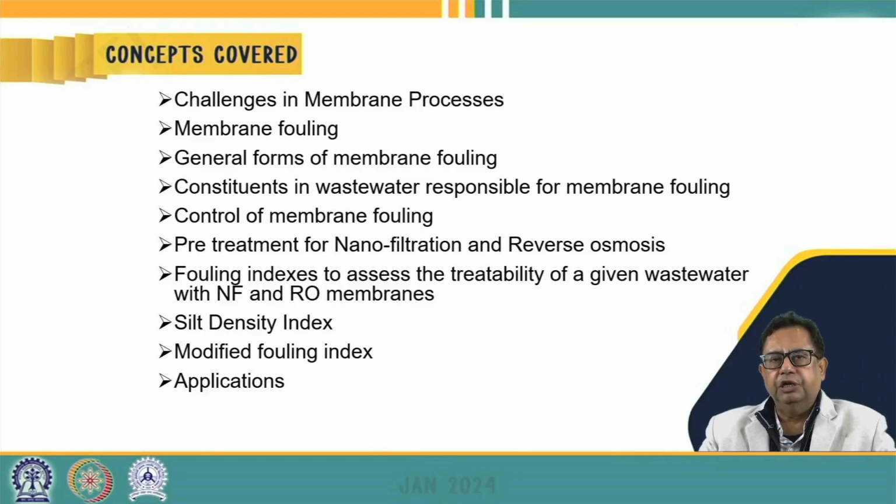Similarly, various indices are used for finding out the treatability of the given wastewater by using nano-filtration or RO membranes. We will calculate the silt density index and modified fouling index, and cover the various applications of the membrane processes in water and wastewater processes.